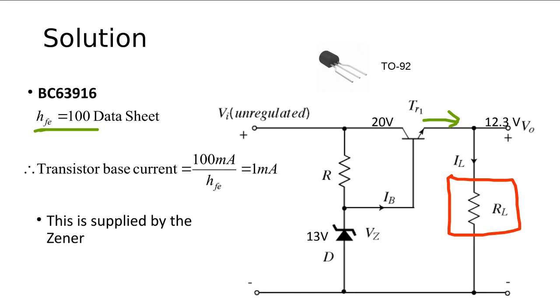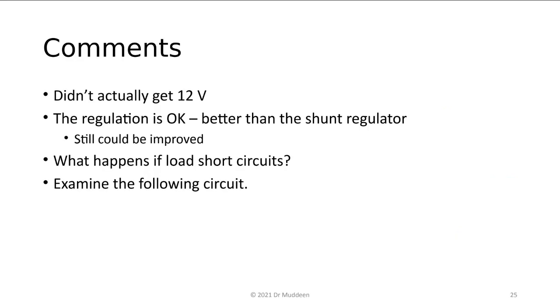And if the transistor burns, well, the power supply fails. If the transistor doesn't burn first, then remember the current is coming from your diode, your rectifiers, and the capacitor. So if the current overloads the diode and the capacitor, somebody is going to blow before the thing eventually shuts down. So you always have to cater for that kind of thing.